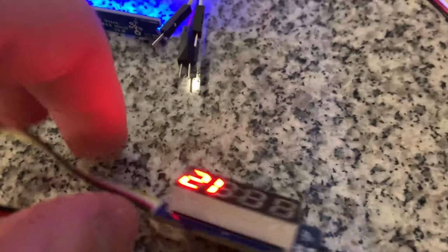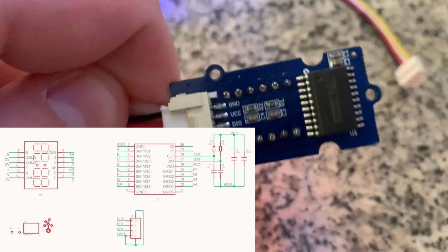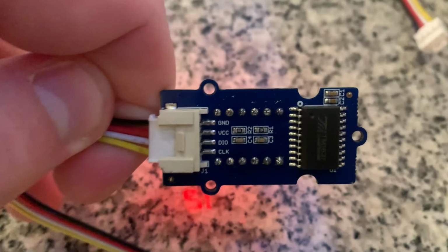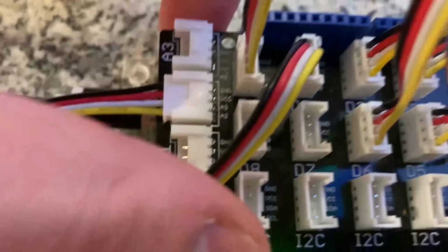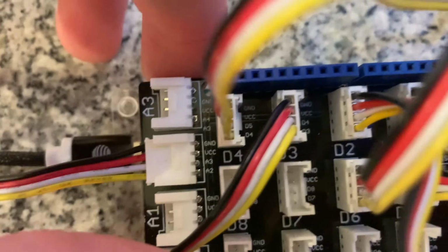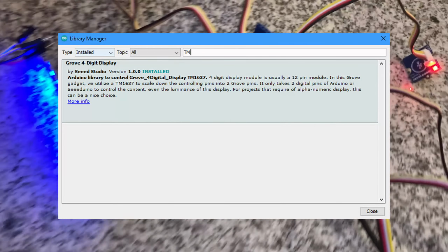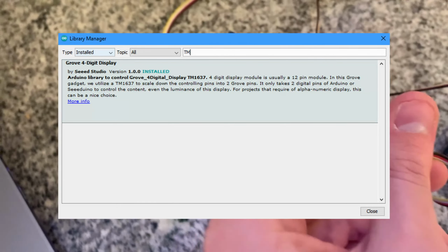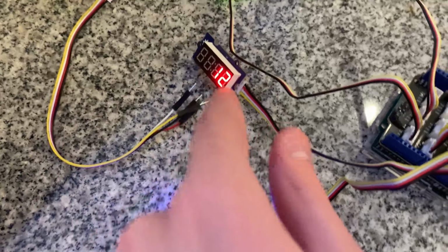as the pin IO. So for something more complicated like this clock, we will need 2 signals, but this time we have a digital input output signal and a clock signal. So white is our digital input out, which is going to be our D5 line, while our clock is going to be D4. And then there's a library that was provided when I got this module that basically gives you an easy way to set up a class object for this guy.